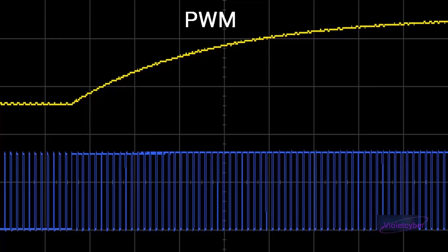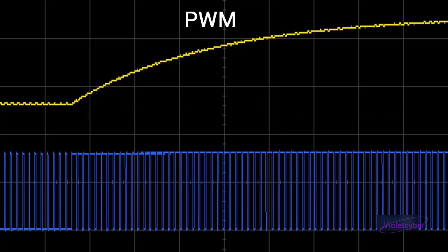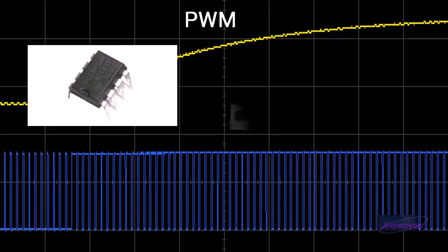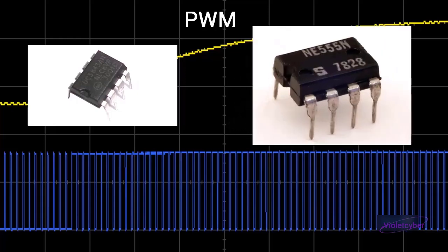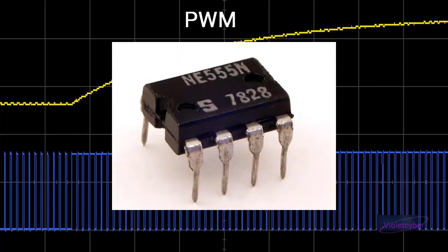First of all, let's see what PWM is. The word PWM stands for pulse width modulation, and gradually you will understand the reason for this naming well. But it is better to know that PWM is actually a type of signal that can be created by various types of microcontroller ICs or various ICs, like ICs that generate pulses. In the market we have ICs that generate pulses, which are also widely used in power switching, also called timer ICs, such as the 555 IC or other similar ICs.